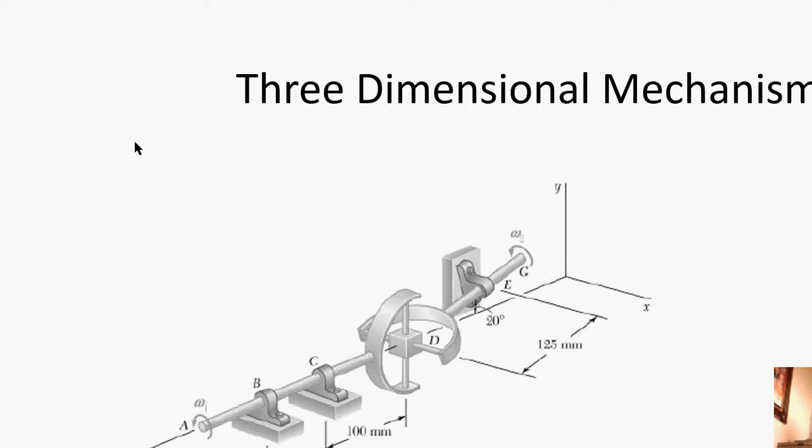What I want to tell you is that you can now do your model normally in SolidWorks, whether you start in inches or in the metric system. It doesn't matter, as long as before you save it as a step file, you change the units to meters. Then when you open it in SimWise 4D, the dimensions are going to be okay.